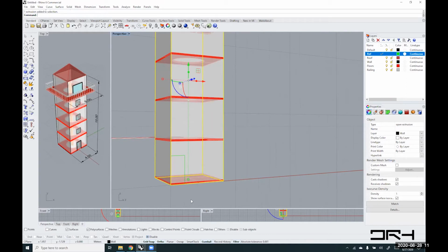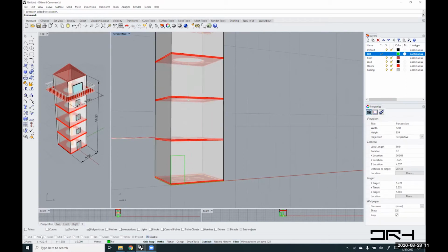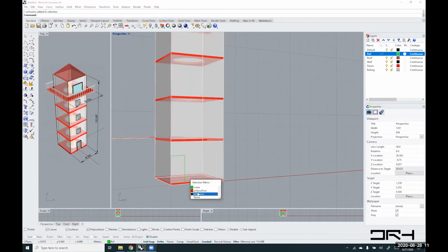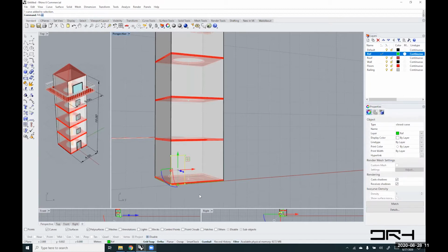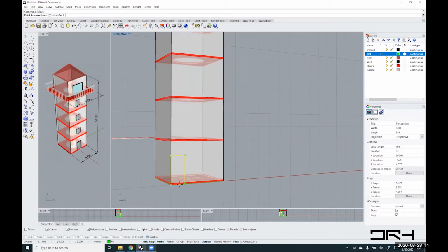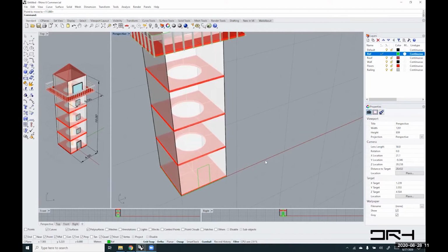Select. Sorry, I don't have the curves turned on as a selection. So I'll select the curve that I just created and move it to center. Starting with the midpoint, I'll turn on my OSnaps. Now they come in handy. I don't want the center, just the midpoint here to the midpoint of this curve. So now I was able to kind of center it